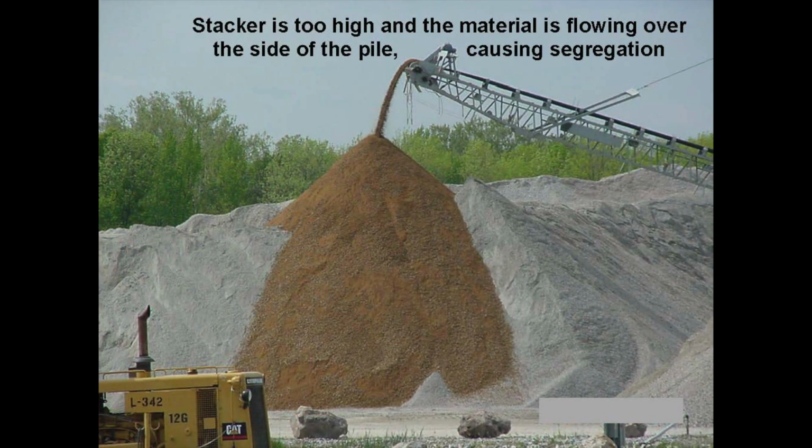So we want to keep our stacker as low as we can. The other thing we want to do, and this could apply to you guys if you have drive-over hoppers to stock your material at your plants too, look at how this is segregated here. Because we're dumping it over the side of the pile, the more opportunity you give that material to roll, the more it's going to come apart. It just has to do with the gravity and the different size particles that it's coming through.